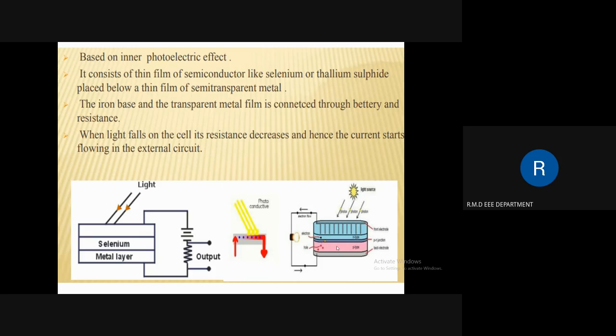The maximum voltage and power dissipation, the dark resistance and the resistance under lux illumination are all given in the representation. The light wavelength that gives the peak response is known as lambda p. The cell sensitivity gives the cell current for a given voltage and a given level of illumination.